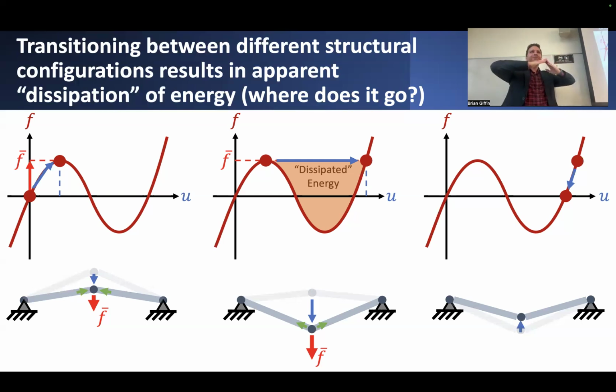For snap-through buckling to occur, the structure has to go from here to here in basically a split second, if that, instantaneously. There's no way the laws of physics would permit the structure to go from here to here in effectively zero time. The inertia of the structure should technically constrain it from instantaneously reverting into this alternative configuration.